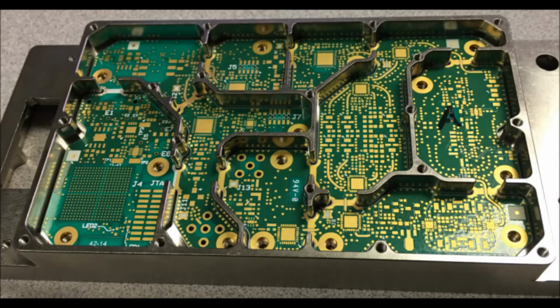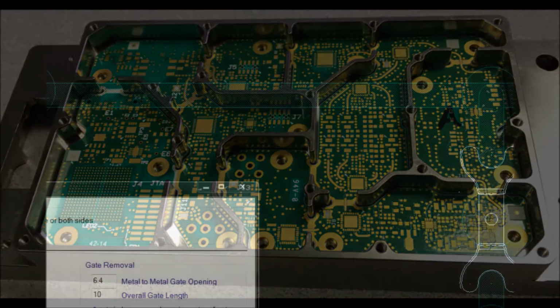When drawing the walls using simple user layer lines, it is easier to draw them without the gates at first. This is mostly because the gates will be a specific size, and it would be difficult to know exactly where to start and end the drawn lines. The software includes a gate removal function to subtract the gates from the walls based on the size of the gates. The PCB designer will most likely work with a mechanical engineer to determine the size of the gate part. This information can then be used to set the gate size parameters in this tool.